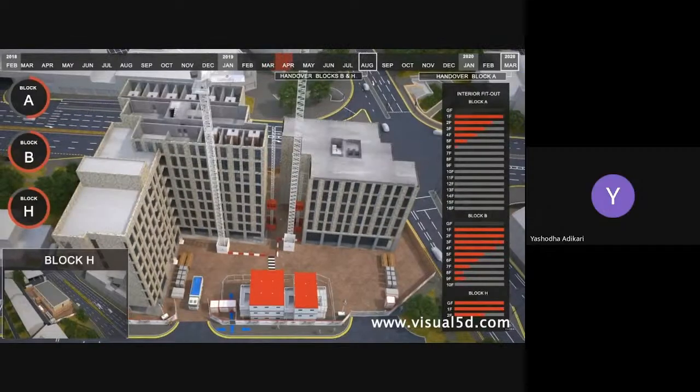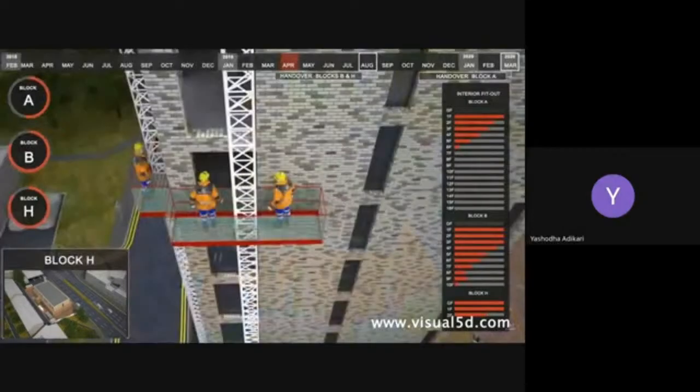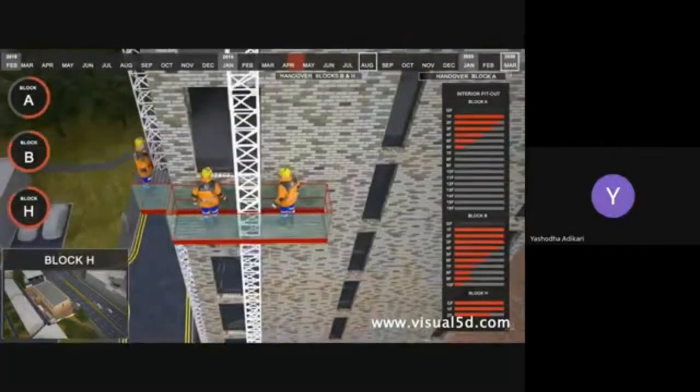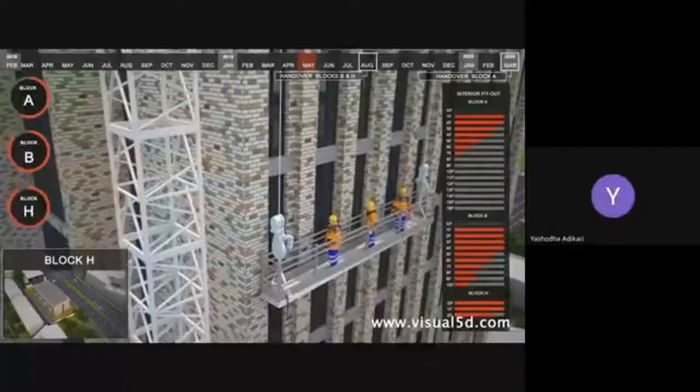The hoists will be installed progressively as the frame is built, along with the areas of curtain walling progressing upwards on this logic. The same logic will be repeated in Block A. Commence the final ceiling works to the facade using cradles.